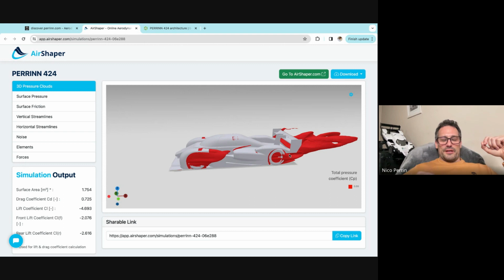That will straight away create more drag and downforce, and then once you know the downforce level at the rear with the drag associated that you want, you're working your design at the front to rebalance the car. Anything you do at the front doesn't affect drag so much, but it's there to rebalance relative to the rear downforce you've got.